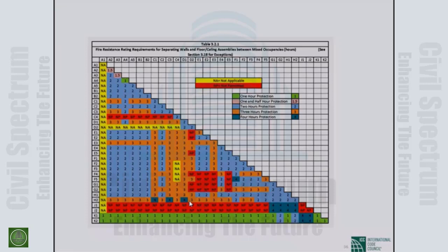So you see, if you put all these buildings together, you have to give proper separation. If you do not give separation, you have to make the building with the most critical one. So you understand. When you like to make, for example, a D1 hospital, and your hospital has some medical college attached with it, that is B1 or B2. Think about the B1, B2 and the D1 hospital, then you have to give 3 hour separation.